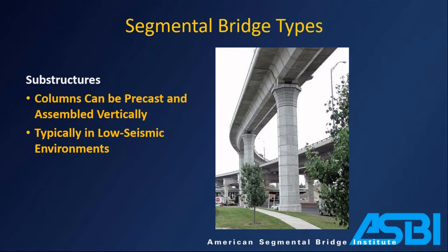So when and where do these make sense? They make sense from the point of view of speed. They come together very quickly, but there's a little bit of fuzziness when it comes to how well they do in seismic zones. I don't think the ductility requirements are well understood or appreciated in a lot of places that have high seismic, your Californias, Washington, what have you. Typically you don't want to see these, but somewhere like Texas, it's a much easier sale when they make sense.